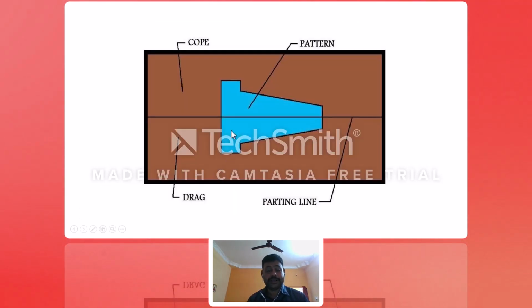So this is called the mold box. This is the upper and lower, cope and drag. You can put it as C and D. C means cope, D means drag. Here the upper half of the pattern is lying in the cope, and the lower half is with the drag. This is the way we have to arrange it, so that this material completely is called the mold material. If it is a sand casting, this is sand. Or if it is a permanent molding, this might be metal.